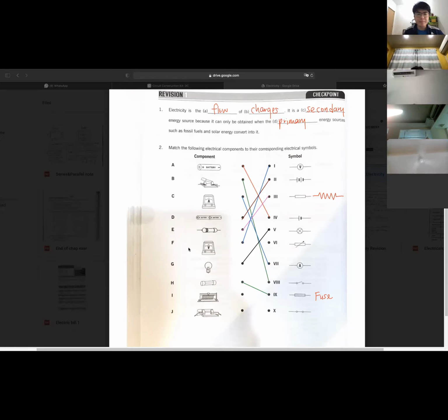If you use more length, that means higher resistance, because even wire carries resistance. Compare a short wire and a long wire: if the charge moves across a very long wire, that's higher resistance than a short wire. So we are adjusting the length of the wire here to adjust the resistance. You can think of it like a coil of wire with a slider on top. So it's a variable resistor. That means we can control the resistance by controlling the length of the wire.